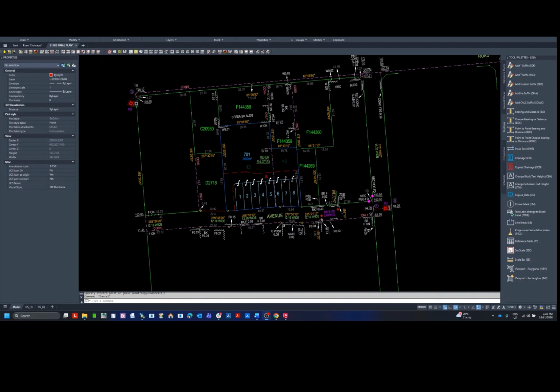Running chainage, how to get it right. It's important to use the latest template and the latest chainage block. You can tell if you've got the latest block loaded in your DWG because the name of the block is CHAINAGE in uppercase, and you can use this to verify you are using the right one.